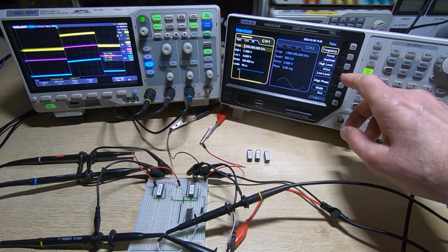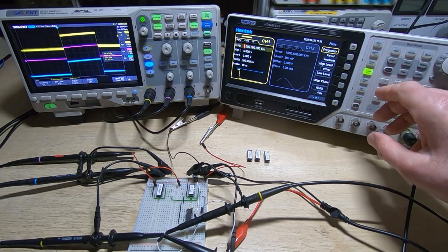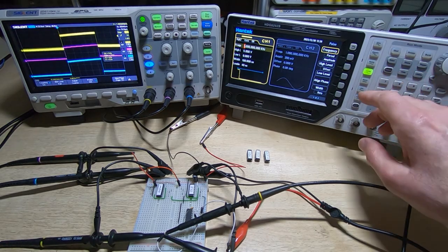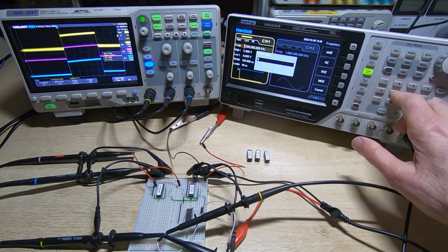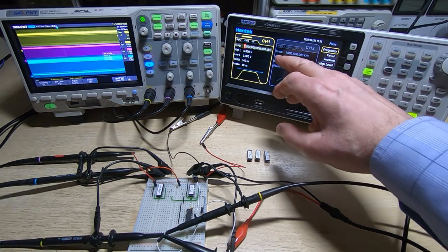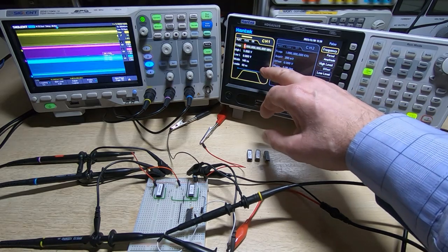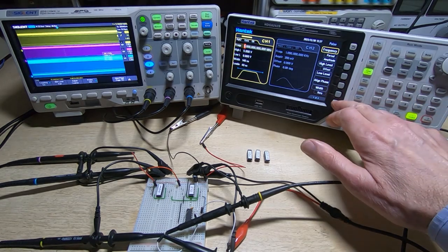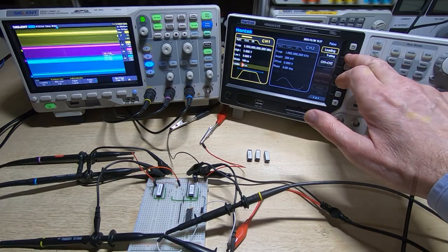So we'll set up the signal generator to give us the frequency that we are trying to simulate. So in this case we want to set it for 5 MHz, and the pulse width we'll set to 100 nanoseconds, because that's kind of the pulse width that we would normally be expecting to see on the individual clock cycles within a system. So I'll just finish setting this up.